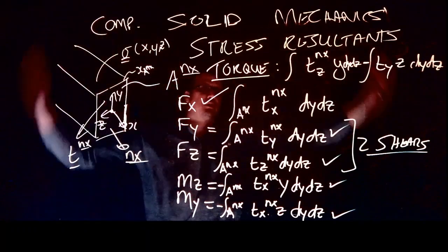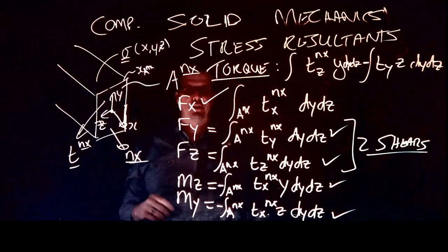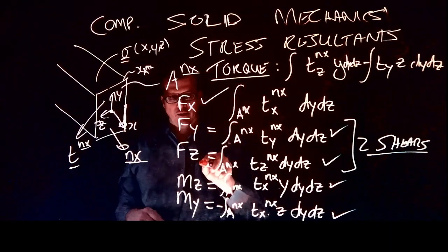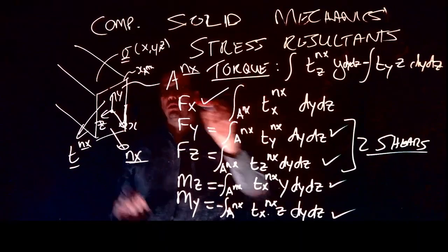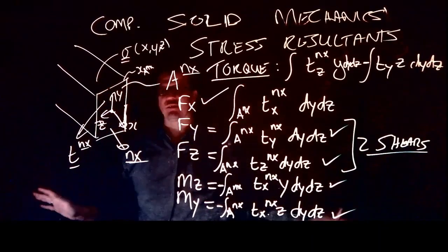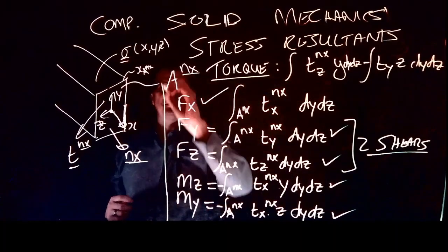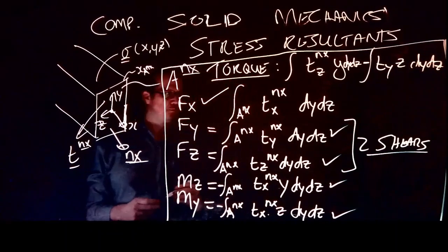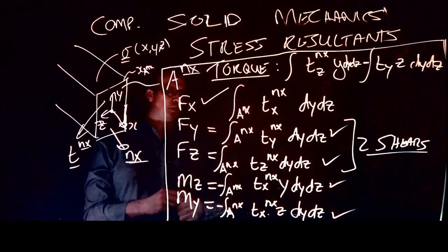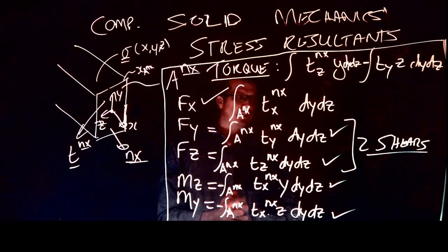But the bottom line is this is what we have, and here we have our torque as our 6th component. So we can compute 3 forces, 1 normal and 2 shears, 2 bending moments, and 1 torque acting on that face, and that counts for every face. These 6 things you must be able to compute with comfort. I think you've done this in other courses, in MOW227 briefly and MSY310 quite extensively. If not, please make sure you recap that material.